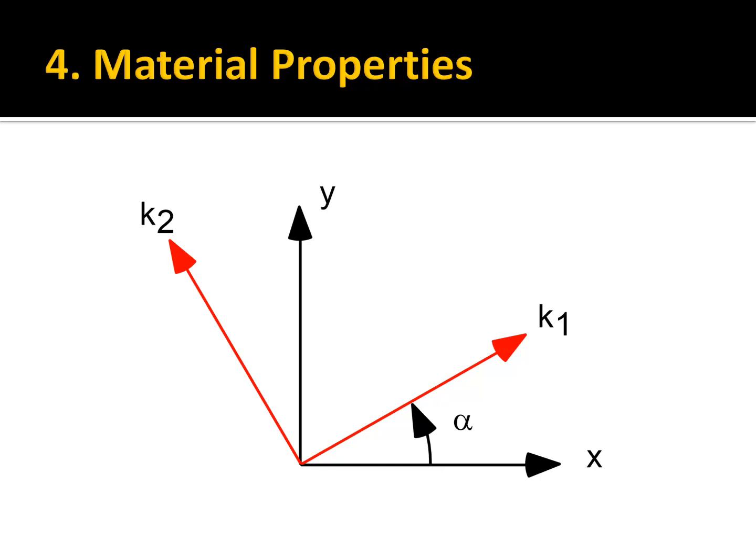So anyway, those are the main inputs for SEEP2D. Once you set that up, you save and run in GMS, and it generates a flow net distribution of heads and flow values. And there are a number of ways to visualize that. We're going to go through, I think, 3 days of examples, looking at all different varieties. This is the culminating method that we'll review this semester. Again, it can be used for just about any profile problem, and so we'll have a good opportunity to explore that. But those are the main features of SEEP2D.